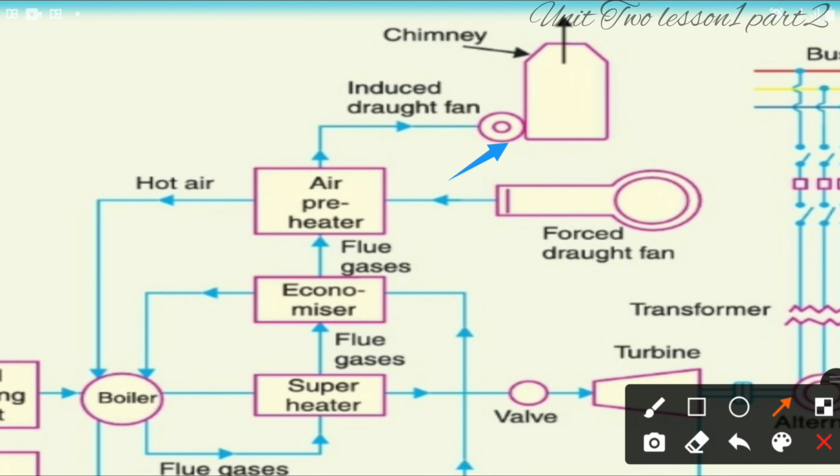So why do we have superheater here? The steam produced in the boiler is wet and is passed through a superheater where it's dried and superheated. Superheater provides two basic benefits. First, the overall efficiency is increased, and second, too much condensation in the last stage of turbine is avoided.